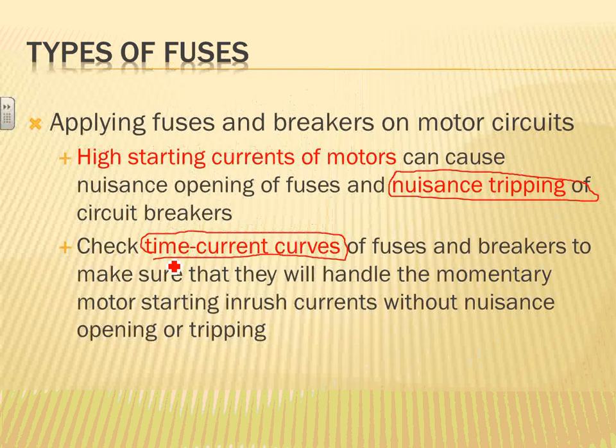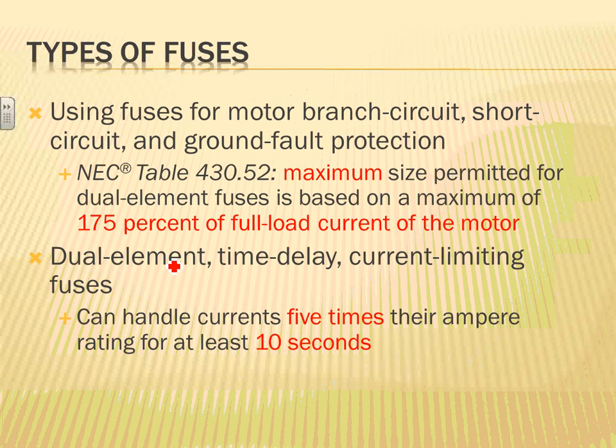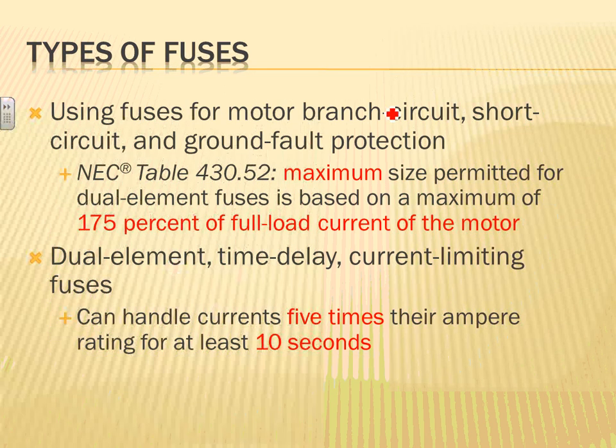I'll show you where the inrush is; we have a starting curve for every motor, and you guys have SKM Power Tools for Windows. There is no reason not to do this every time you have a motor. You go check how the circuit breaker is set, instantaneous or fixed, to make sure the circuit breaker will clear the inrush. I'll talk about this one a little bit more when we talk about motors.